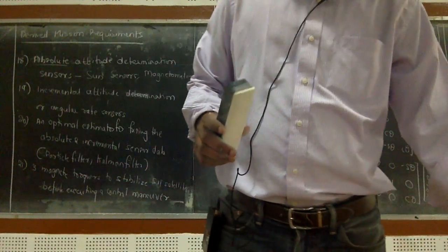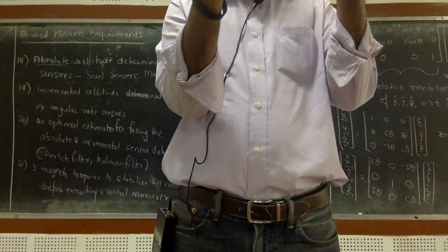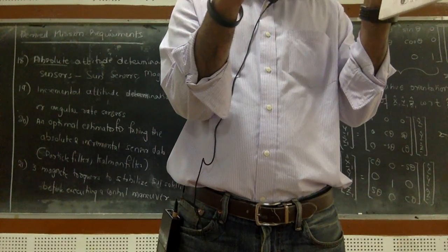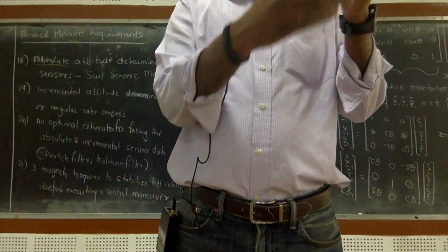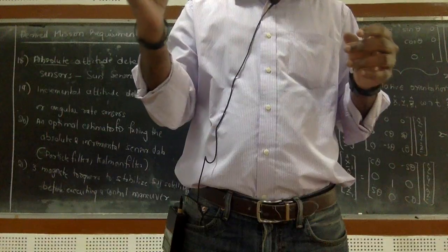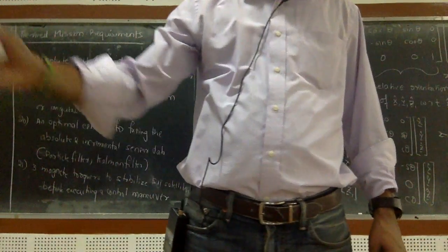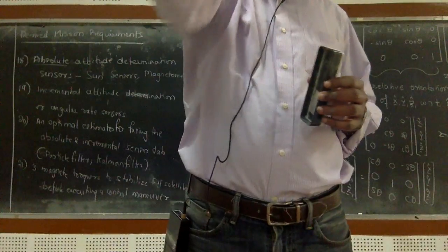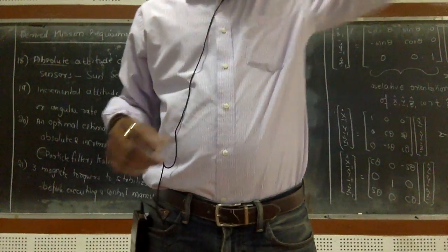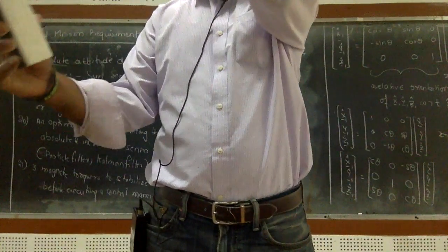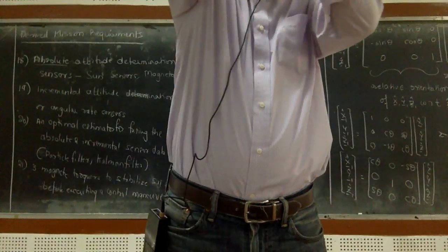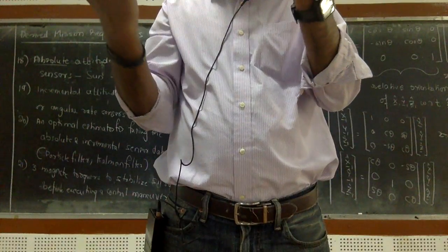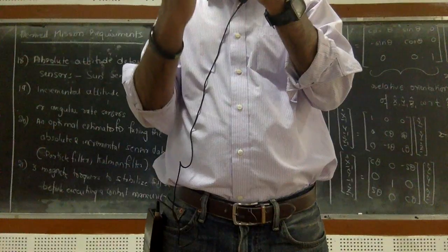If my sensor is pointed like this, correct? Which face is facing the sun? Possibly the longitudinal face, right? Even if it is going like this, it's a polar orbit. Where is the sun in the polar orbit? That side, right? So if this is Earth, and the satellite is going like this, where is the sun? It's on that side. So this face is facing the sun, and the face which is capable of producing maximum solar energy is facing the sun.